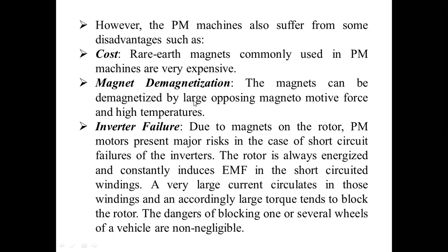The next one, inverter failure. Due to the magnets on the rotor, permanent magnet motors present major risks in the case of short circuit failures of the inverters. Here, the rotor is always energized and constantly induces EMF in the short-circuited windings. A very large current circulates in those windings, and accordingly, torque tends to block the rotor. The dangers of blocking one or several wheels of a vehicle are non-negligible.